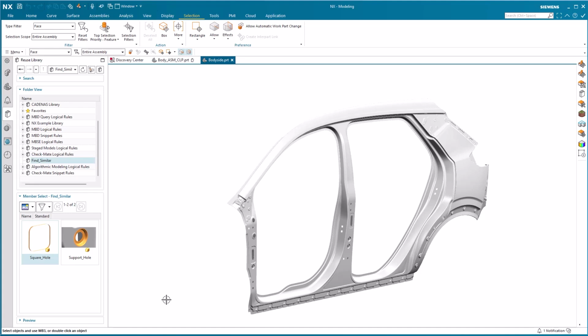In addition, you have also seen that the Reuse library contains some predefined shape regions and works with the Select Similar Faces tool. Finally, you have seen how to use the predefined region objects and the speed of using them together with the Select Similar Faces tool, where all the search criteria is already defined and how that makes you much more efficient in the selection process. This concludes this tips and tricks session on the use of predefined shape regions while in the Select Similar Faces tool.